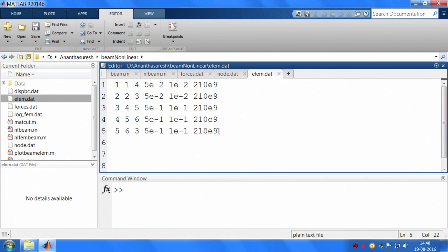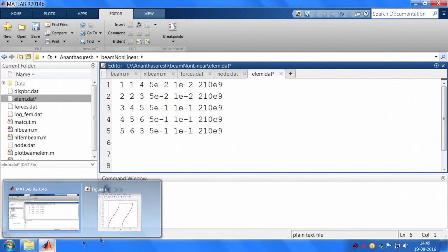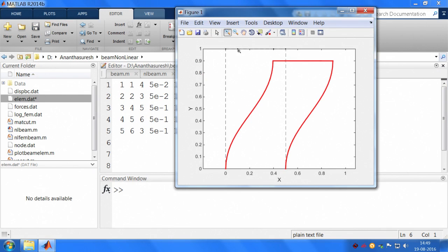So I already have 5 elements. Now I want to add 2 elastic segments and 2 rigid segments. So 2 elastic segments, again if you go back to the figure, I have to hang from that node to this node that I have created, and then that node to this node I have created. In between I have 2 more, that is from here to the center of gravity to the other one of the